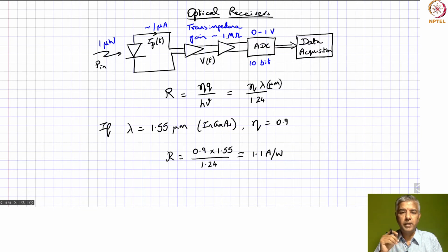What that means is you can get 1 meg transimpedance gain using this op-amp, but only for 1 hertz of bandwidth. On the other hand, if you want at least 1 kilohertz of bandwidth, you are limited to a gain of only 1 kilo ohm. Issues like that can put a limitation on this, and we will come back and look at them in more detail slightly later.